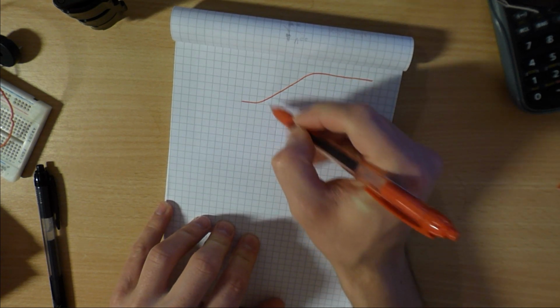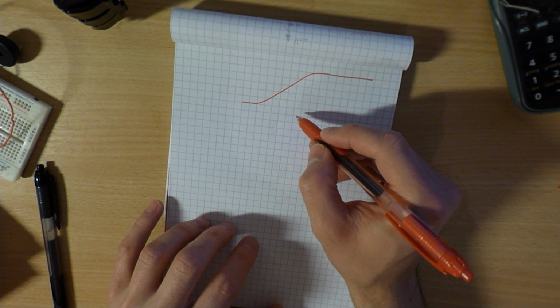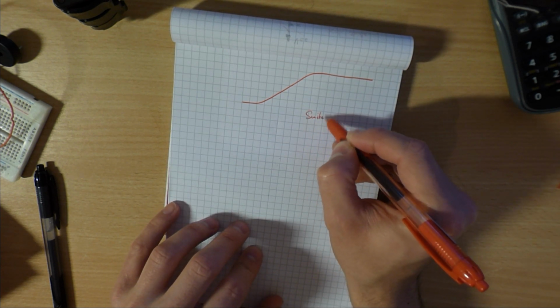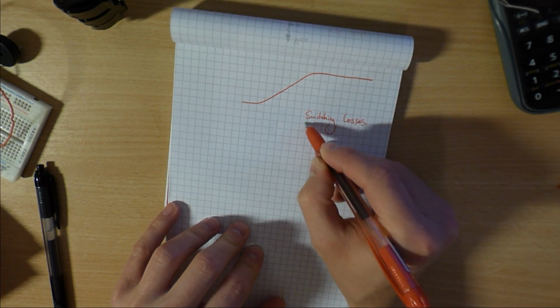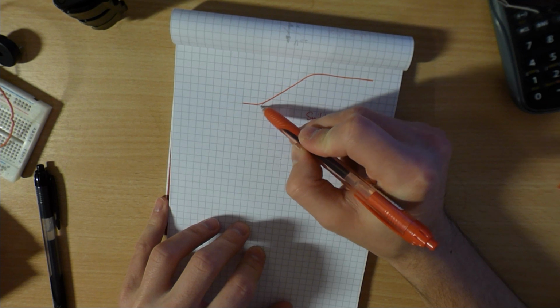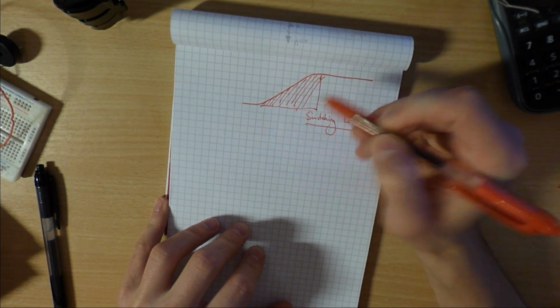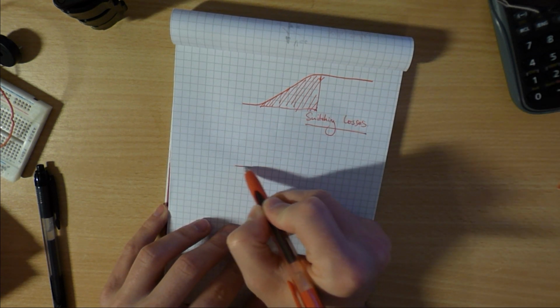There won't be any ringing on it, but you'll have a lot of what's called switching losses. So when the MOSFET is switching, is really the only time that it's dissipating any heat, and so the area under this curve here, whilst it's switching on, is essentially your power loss. So the quicker you can turn this on,